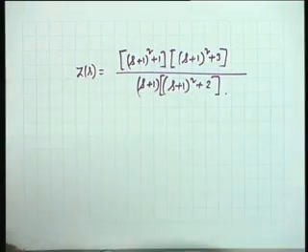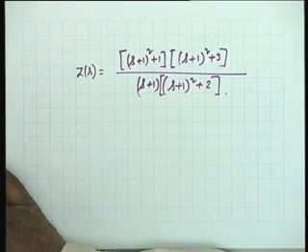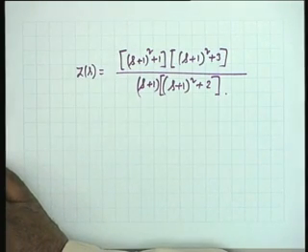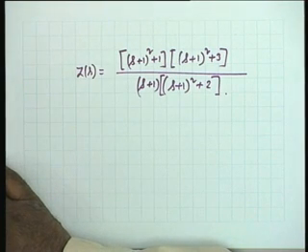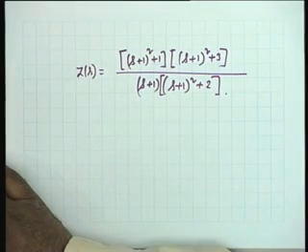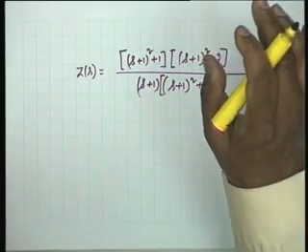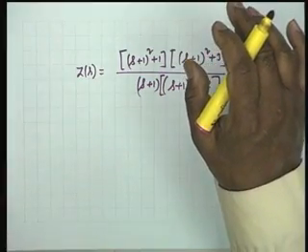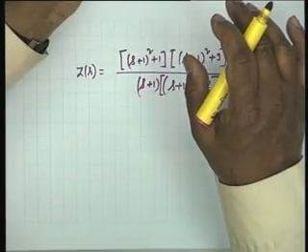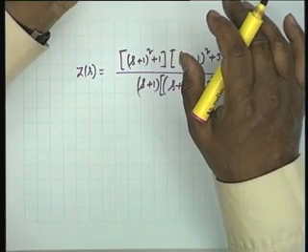Obviously, the function, if at all realizable, if at all PR, it would be realizable as an RLC, neither LC nor RL nor RC, because the poles and zeros are in general complex, therefore RLC network. Now, we have not learnt RLC network synthesis in general, but this problem is of a type which can be